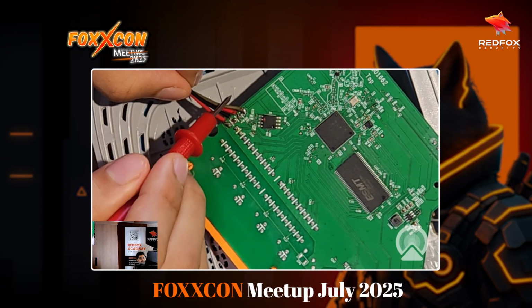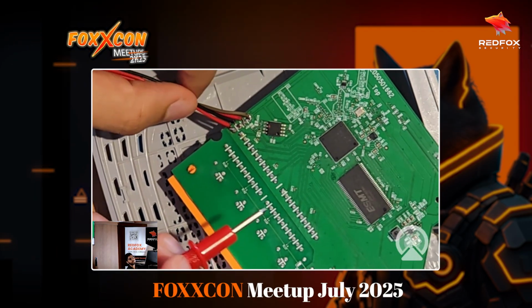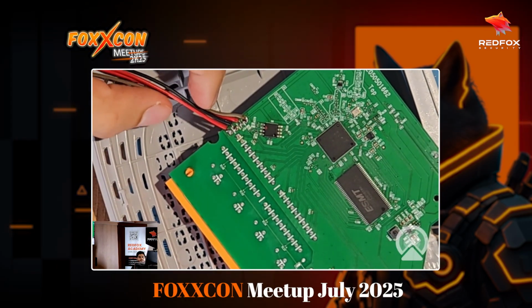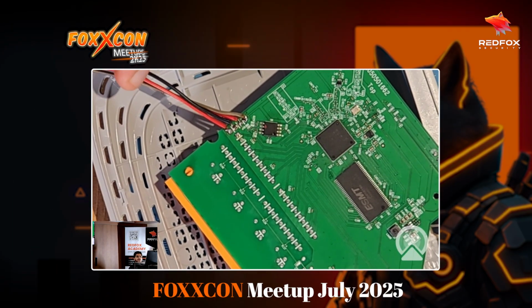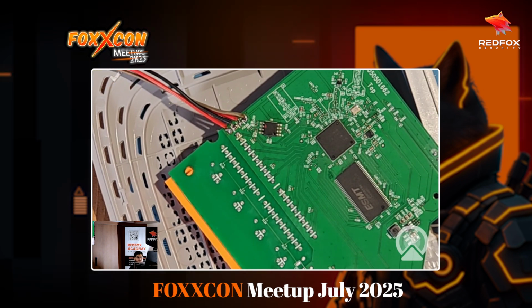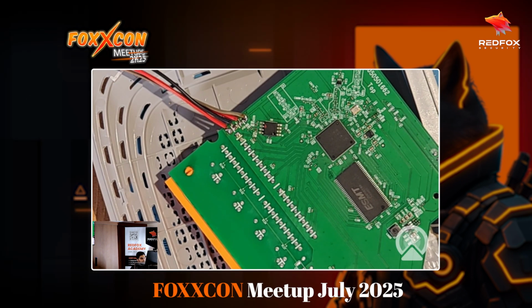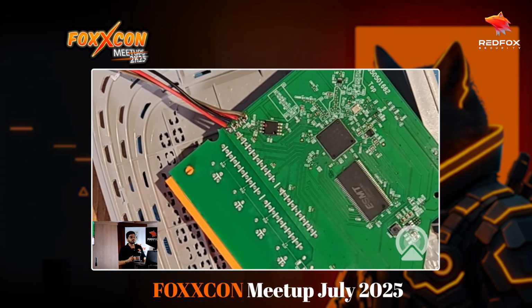We want to figure out the rest. How do we do that? As I told you guys, if you have ground, then you will be able to figure out VCC, which is power as in voltage. So if you put one pin on ground and one pin on anything, and if it transmits a sustainable voltage, that means that is specifically VCC. For us to get any voltage whatsoever, we would need to first power on the device.